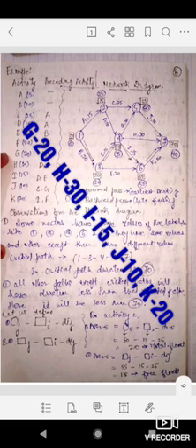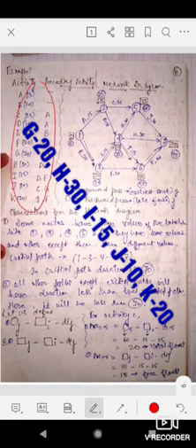So today we will study one more example. I have shown it here: the activities, their time durations, and then the preceding activities. On the basis of this table we will construct this network diagram, or we call it a precedence diagram.